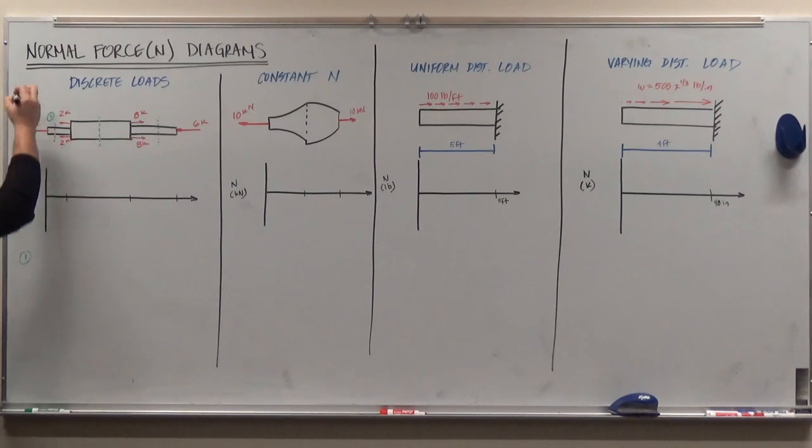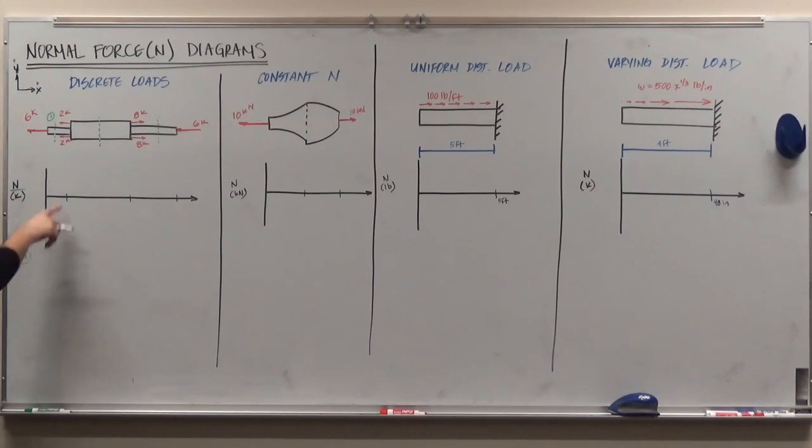And for all of these free body diagrams, I'm going to use the same coordinate system. Y is positive going up, X is positive going to the right. My first free body diagram for this first section cut, I'm going to keep the portion of this column to the left of the section cut. So there is that. Here's my section cut.